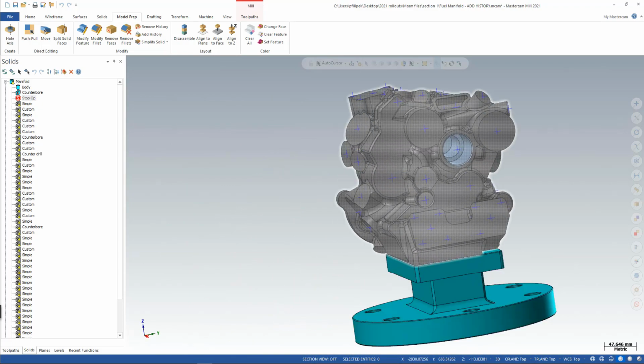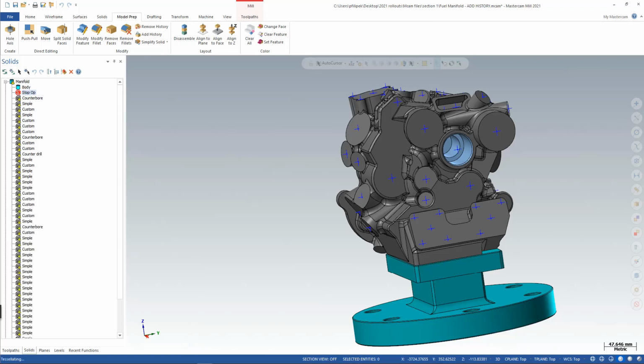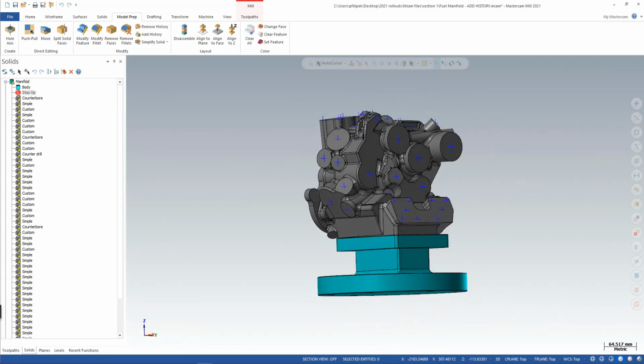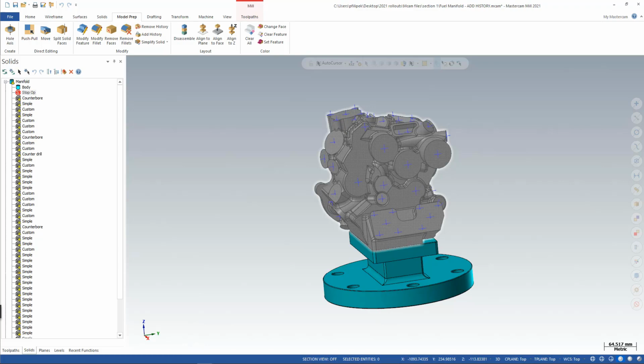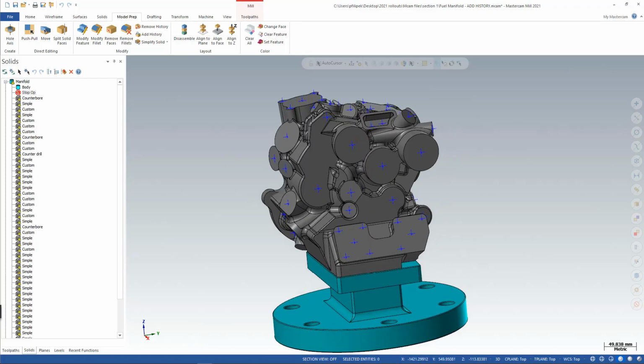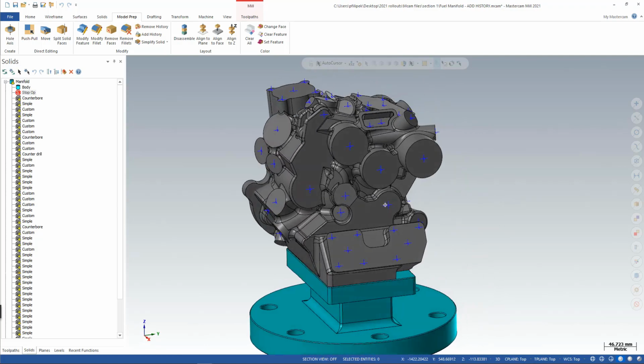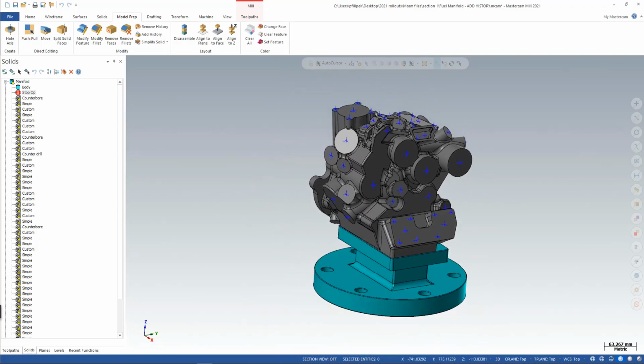part. Now I missed one hole there. So I'm going to drop this right above there. There we go. And now that hole will be disappearing out of there. And now what I have here is a perfect environment for maybe an OptiRough. No holes in the part. This is what I have to rough out before I put any holes in the part. So I could utilize this now for an OptiRough cut or a roughing op.